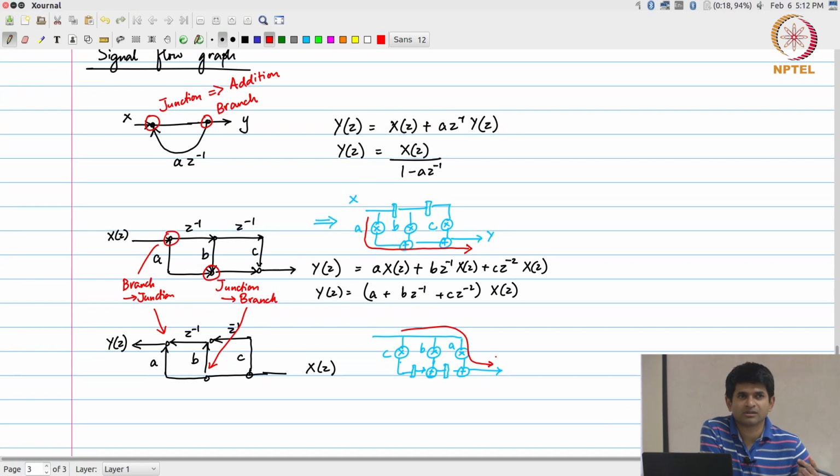Why do you need a big shifter? So that's one very good point. Essentially what is being said is, the x over here will be some number of bits. If this is some n bits, then this will also be n bits, this will also be n bits. But the moment I multiply an n bit value with something else, the number of bits that I actually need in order to represent the result is more than n. If I take two n bit numbers and multiply them, strictly speaking I need 2n bits in order to represent the result.